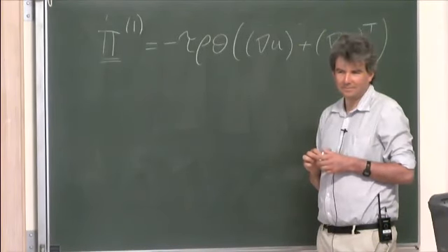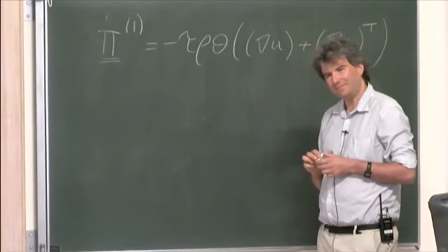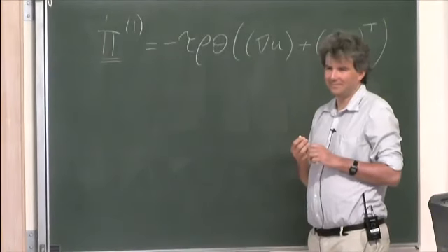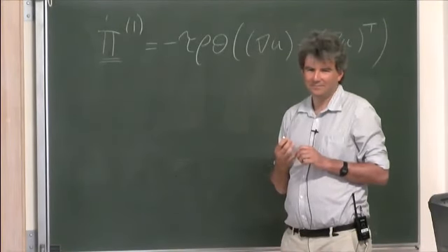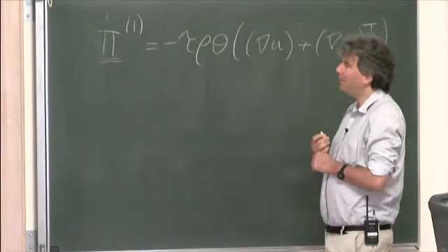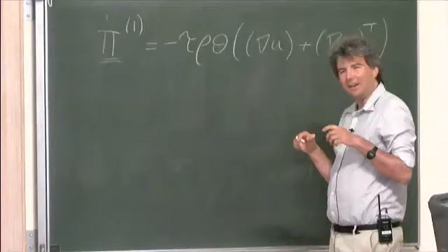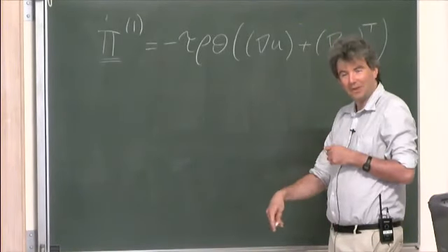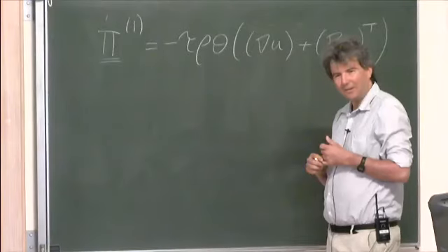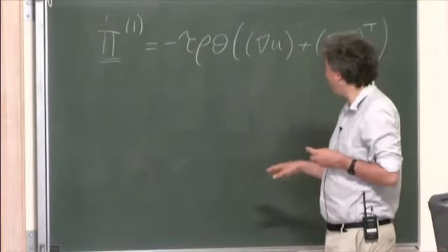There were also things about symmetries that obviously you can't expect to reproduce continuous symmetries on this lattice. Well, you reproduce an isotropic viscous stress, so you've hidden the anisotropy down at the Burnett and higher levels in the Chapman-Enskog expansion. So at the Navier-Stokes level, you do have isotropy. But there are various artifacts of the old lattice gas.